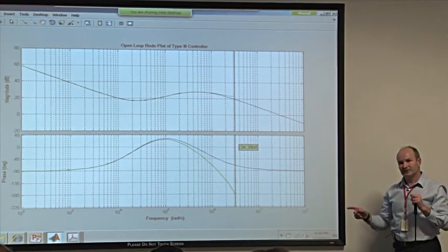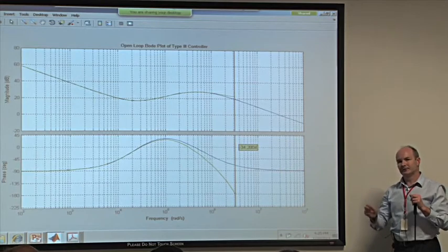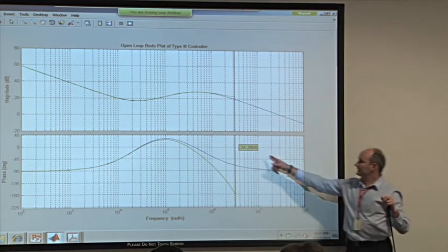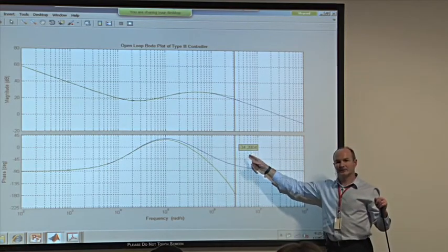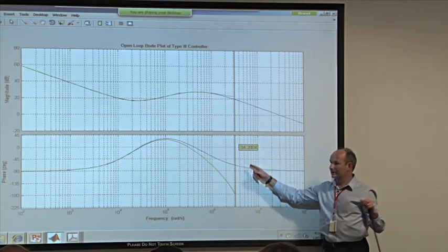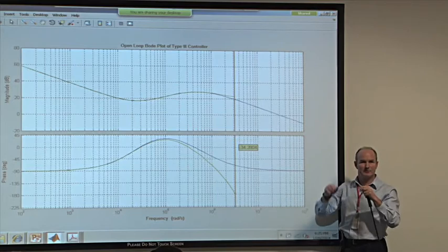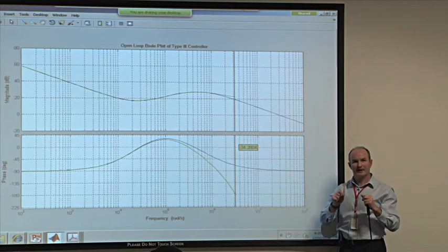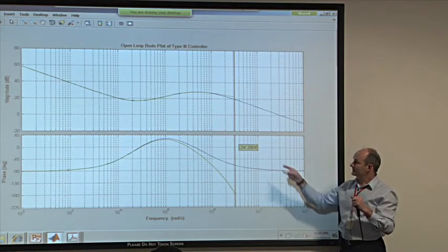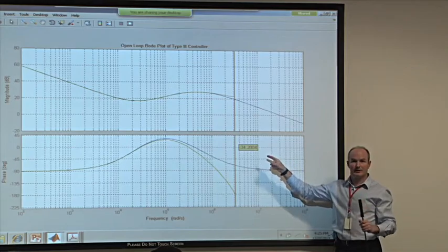And the reason it's the most accurate of all the methods is that when you build your system, you will really find this amount of phase lag, because this is coming from the zero-order hold, the thing that I approximated with that unit step, right? The difference between unit steps. That phase lag is genuinely going to be there. So this is true. This is what you're going to end up with.